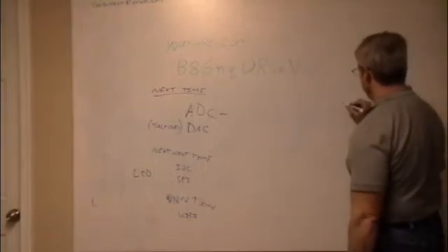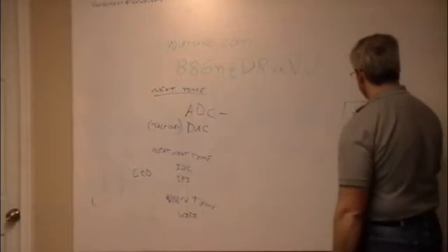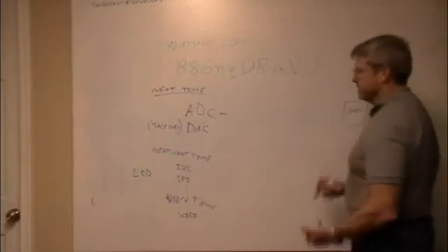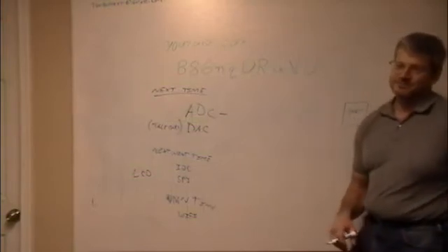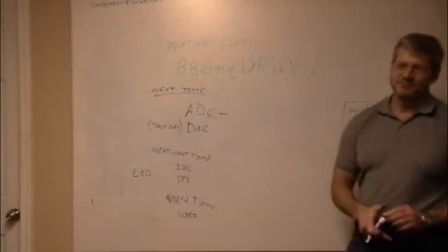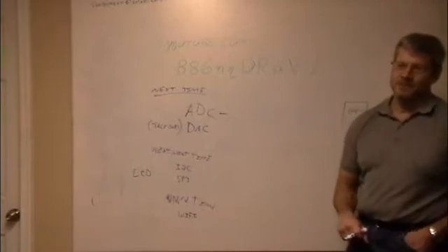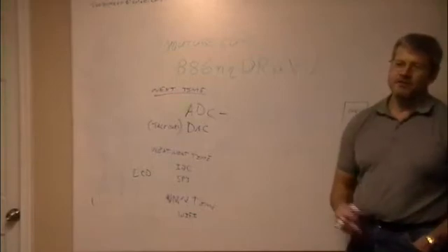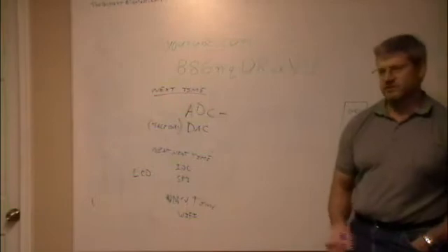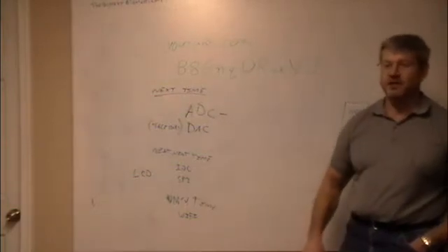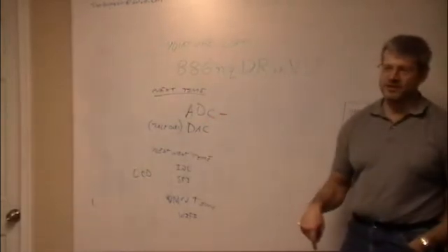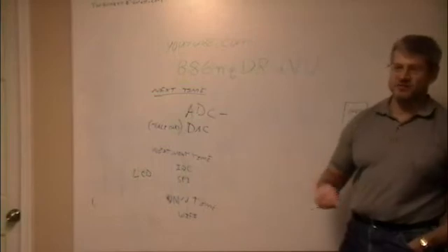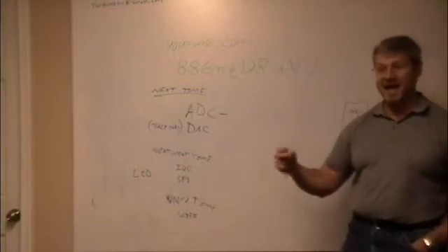You've got an oven, and you can only turn it on or off, right? I would assume that the heating elements have some level of variance in them. They do, but what you find is you can't turn a knob. It's not like your oven. Even your oven at home, when you turn it to 400 degrees, it's got a thermocouple in there, or the equivalent, a bimetallic strip. When it gets a certain hot, it just turns it off. It's called a bang bang control.